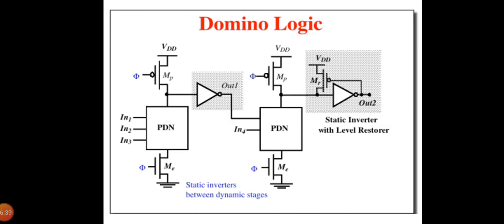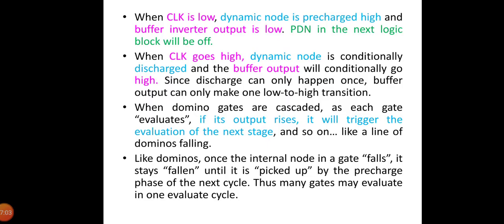The function of the transistors M1, MF1 and MF2 is to keep the circuit static when the clock is high for extended periods of time. It is called a bleeder. So you can notice that this circuit is not ratioed even in the presence of the PMOS pull-up devices. Due to high performance, this differential approach is very popular and is used in several commercial microprocessors.